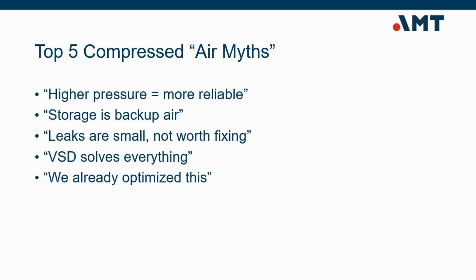Myth number 3. Leaks are small. Individually, leaks seem minor, but collectively, they often account for 20 to 40% of total air production. And unlike production demand, leaks run 24 hours a day. Ignoring leaks is like leaving lights on in every room all the time.